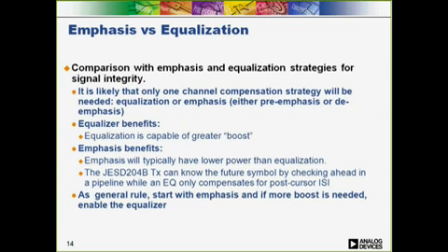An equalizer is generally capable of compensating for more insertion loss than emphasis, but can only compensate for postcursor ISI. Emphasis generally consumes less power than equalization. Also, depending on the emphasis architecture employed, precursor ISI can be reduced. If emphasis is used, the data in the pipeline is known and can be manipulated to reduce the precursor ISI effect, as well as the postcursor ISI effect. We will describe this in detail in later slides.